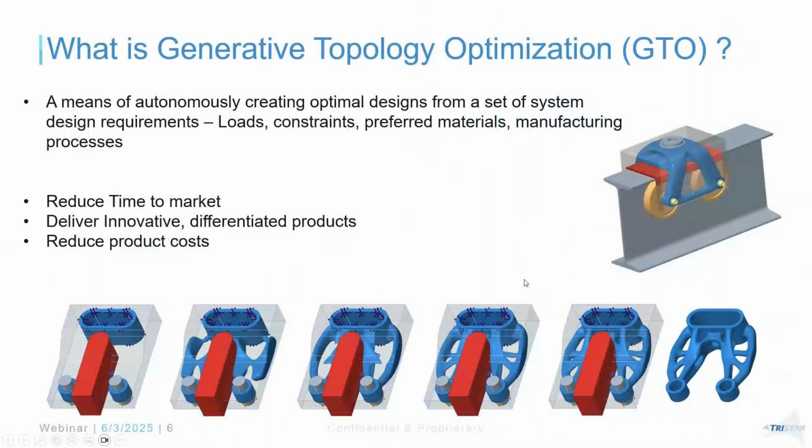Whether it's going to be a cast, if it's casting, maybe I give a parting line. Is it a 3D parting line or a 2D parting line? And I can give the angle, etc., right? So depending on that, it is going to generate a geometry for you, which is very different from many of us when we think about optimization.